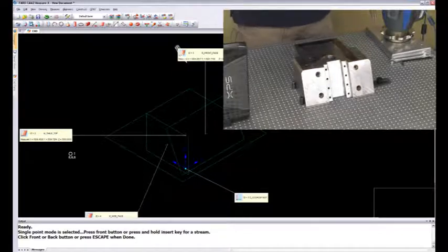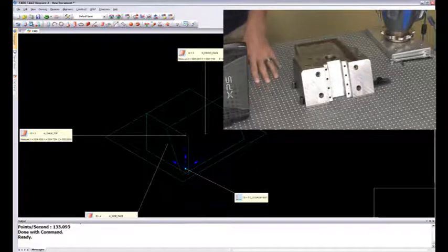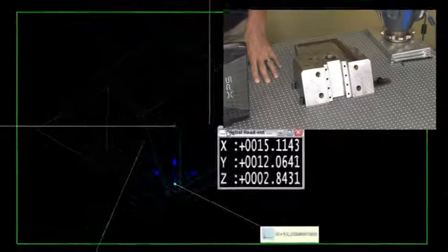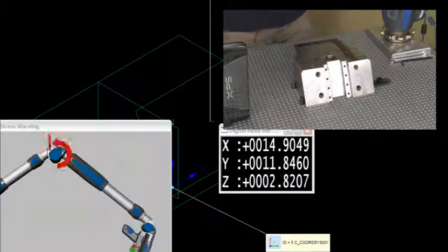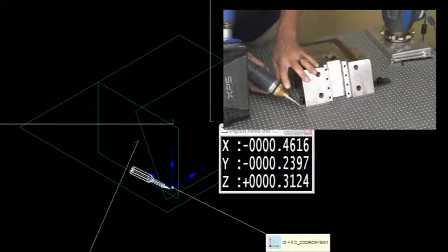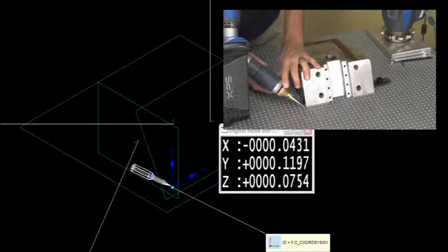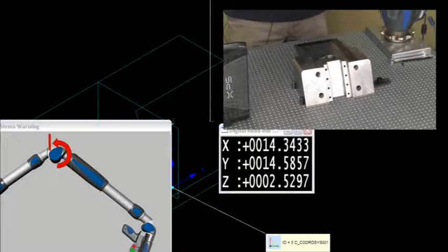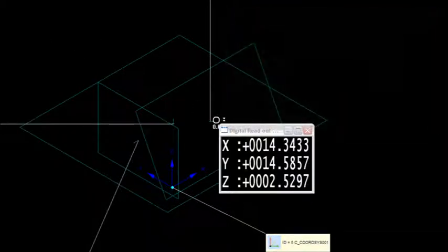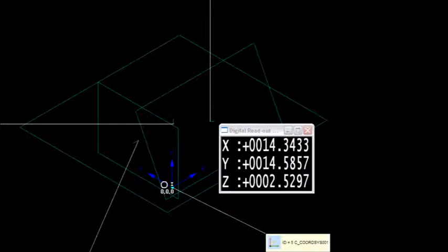In fact, I'm going to bring that in just a little bit closer here. I'm going to pull it right down here. And then I'll go back to the measure, inspect XYZ. And now notice if I'm right into that origin, right into that location where my origin is, my XYZ is pretty close to being where 0 is. So that's what I like to see. That's a good way to double check to make sure that my coordinate system truly is my origin, and that's truly in this corner. And that's set up off that 3-plane constructed coordinate system.